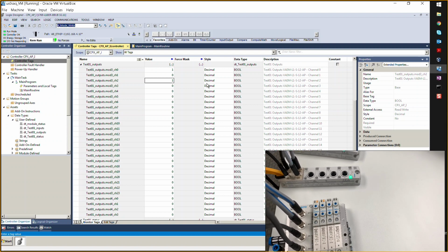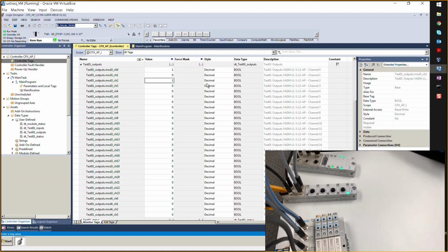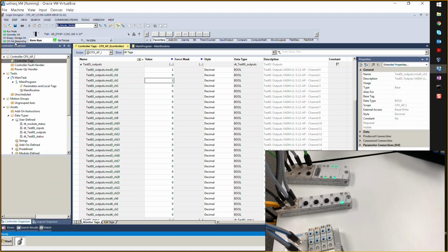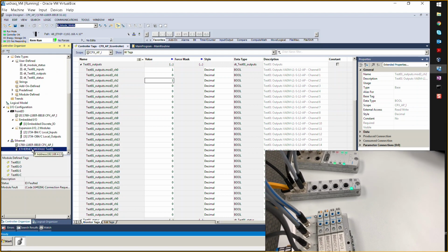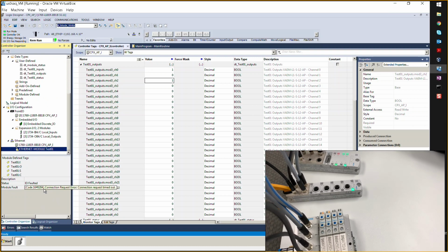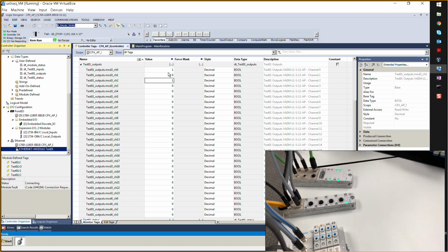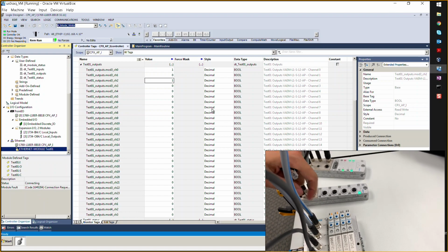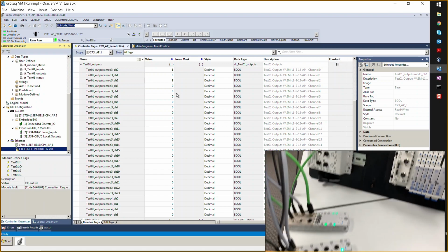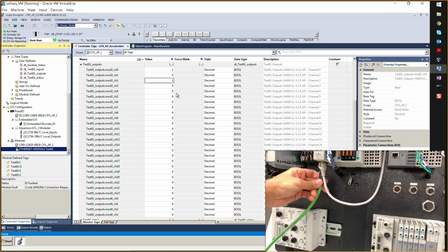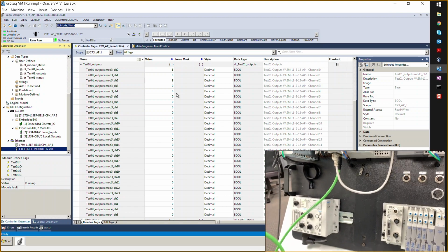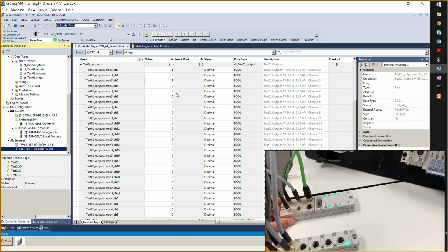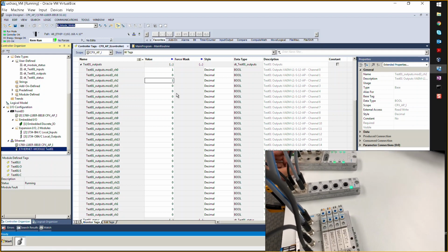Yeah, correct. So yeah, as you can see here, I/O not responding, because these modules should say I/O faulted, right? Yes, which it does. But the valves, the coils remain on. Okay. Yep, I see them physically here. And that's exactly how it should behave. And that's a parameter setting that you've created now. And this is the way to do parameterization with the API system.